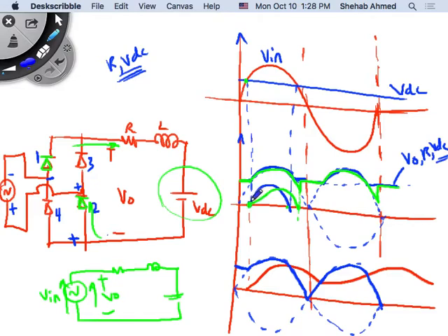So here, the equation for current we've come up with before. We've seen this exponential rise and drop in current, and we know the point at which the DC voltage is equal to the AC voltage. That's the current inception point, where I of alpha equals 0. How do you find alpha? You equate VDC to V max sine alpha for the sine wave. You solve for alpha, and you have your inception point, so I of alpha equals 0.